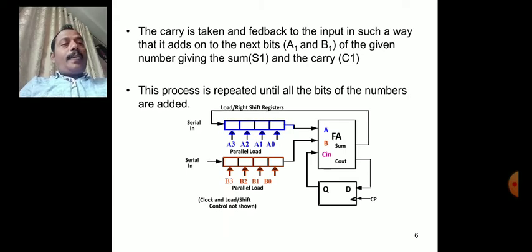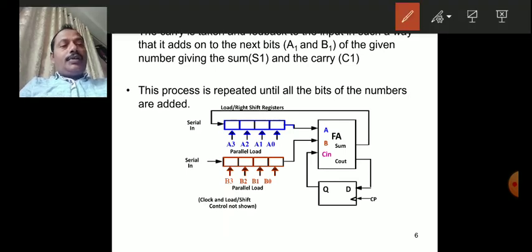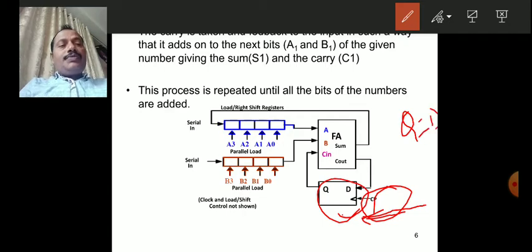You see, so this is the one. That means once the clock pulse comes here, for every clock pulse, this is the new time instant. That means the shift operation happens, and the delay flip flop output Q equals D. Whatever output is produced is shifted to here.